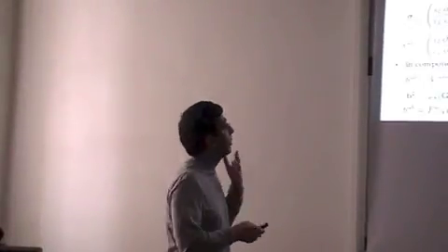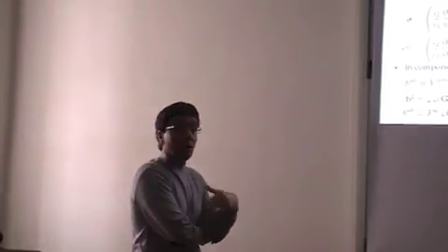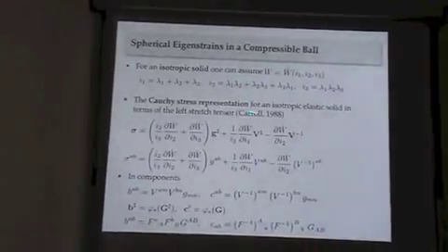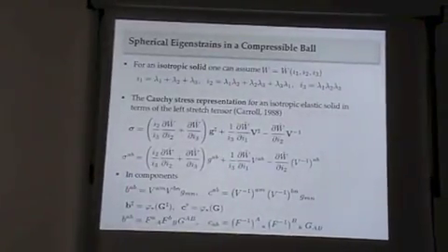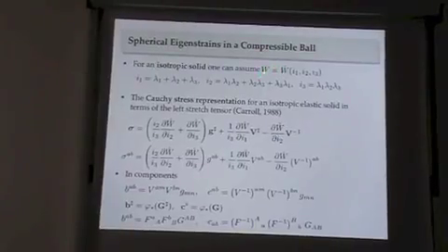Now, what about compressible? I can do it for arbitrary compressible solids, but I'm going to look at a special class of compressible solids due to Carroll. Instead of saying W is a function of lambda 1, 2, 3, we could look at the principal invariants of the stretch tensor, which look like this. If you do that, you would have this representation for the stress tensor. This is what Carroll wrote when everything is Euclidean, so I simply extended that. It's just an easy exercise, and geometric.